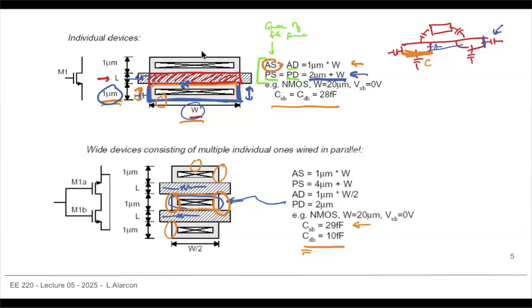Again, if that is connected to your output, let's say you have an amplifier and that's connected to your output, and it's driving a cap, then if this is already a very large cap or you want very high frequencies, I don't want any other things connected to that output. Maybe I want to minimize that particular output capacitance.